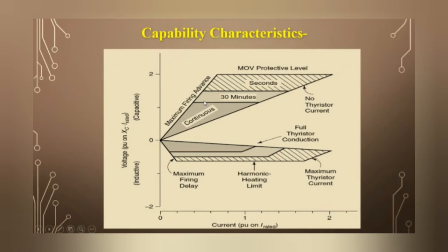The maximum capacitive reactance is chosen based on the TCSC design so that the TCSC does not venture close to or into the inherently unstable resonance point. So here we select the XC value so that the TCSC module does not go to the resonance condition. The maximum XTCSC is typically 2 to 3 pu, expressed in per unit of XC. See here, the maximum value is 2 to 3 pu.